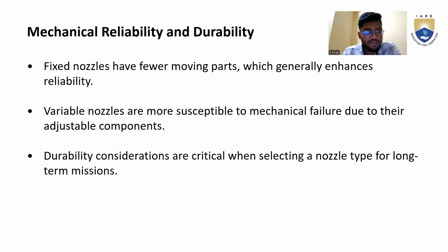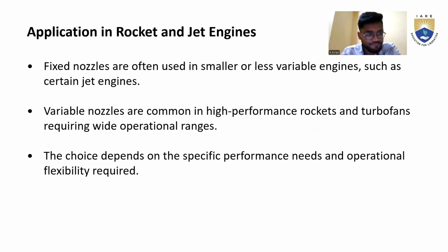Now here we can see and observe mechanical reliability and durability. Fixed nozzles have fewer moving parts, which generally enhances reliability. Variable nozzles are more susceptible to mechanical failure due to their adjustable components. Durability considerations are critical when selecting a nozzle type for long-term missions.